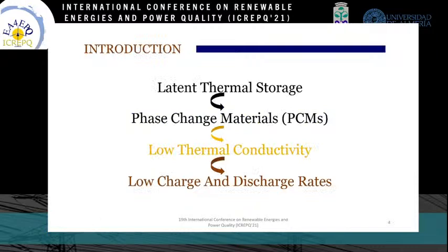The storage of thermal energy is considered to be an efficient solution for renewable applications. Generally, thermal energy storage can be achieved in three forms, namely sensible, latent, and thermochemical. Among these, the latent thermal energy storage system has proven to be the most efficient from the point of view of higher storage density and storage of thermal energy at a constant temperature.